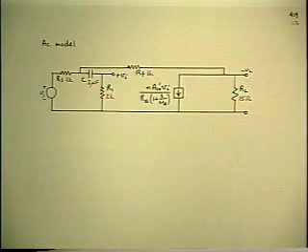The purpose of doing that was that if you put the capacitor in immediately, then you have some algebra to do to get the result, in fact, at pole zero form. Whereas by ignoring the capacitor, that is, replacing it by a short, we were able to get the mid-band value of the loop gain very easily, and then we restored the coupling capacitor using the extra element theorem, and that gives an inverted pole at 30 hertz at the bottom end of the mid-band loop gain,